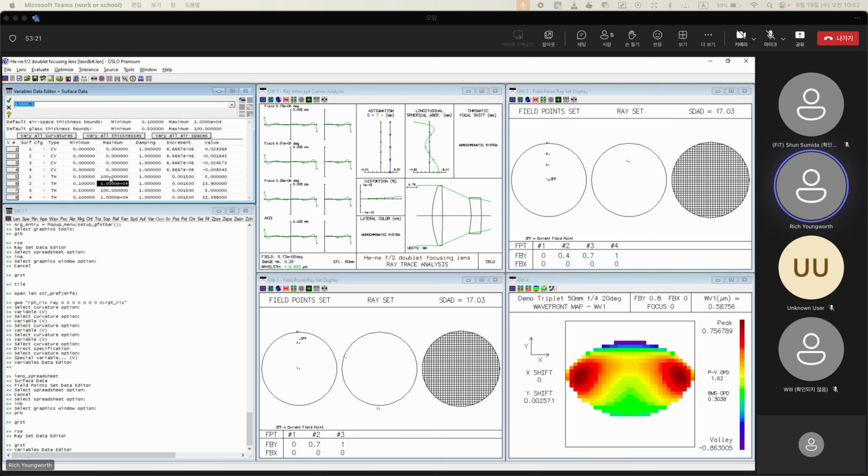Because of that, if we actually try to go outside the bounds, what Oslo will do is put a penalty on the error function. So you'll have the calculation from the error function itself, and then there will be an extra value added onto it as a constraint violation. I had a customer a few years ago send in a support ticket where they couldn't figure out the value of their error function, and it was because it had a constraint violation and they weren't incorporating that.